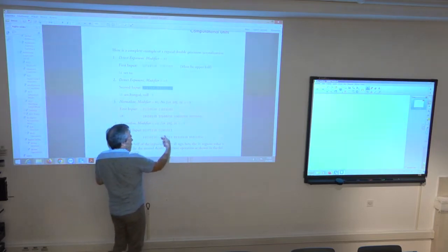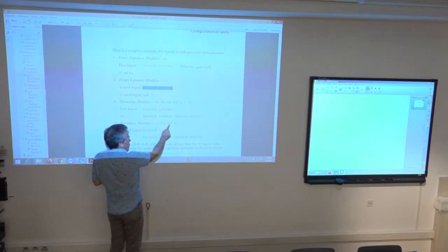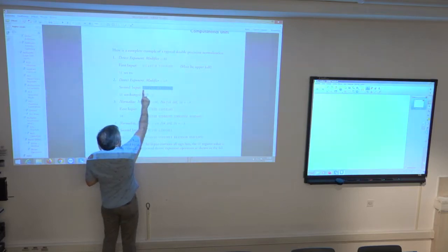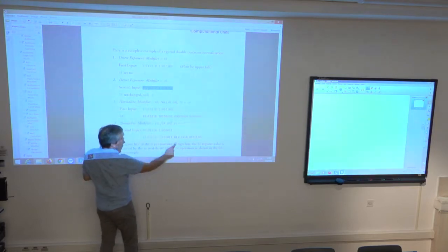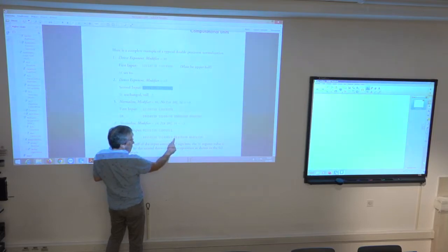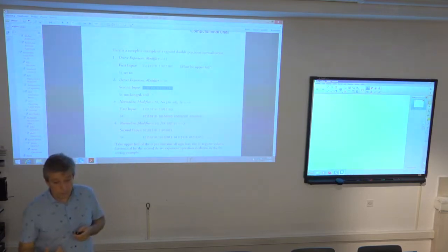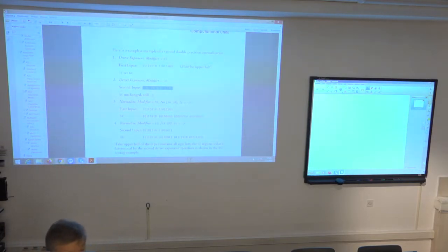But after that, I combine this value with an OR operation and put in another lower word, again shifted by 3 positions. The lower word was 0 1 1 0, so it comes out here as 0 1 1 0. And then you have 3 zeros shifted from the right side in the lower word. So actually with 4 assembly instructions, you can perform exponent detection of a 32-bit value and normalization of this same 32-bit value by a given detected exponent. Okay?